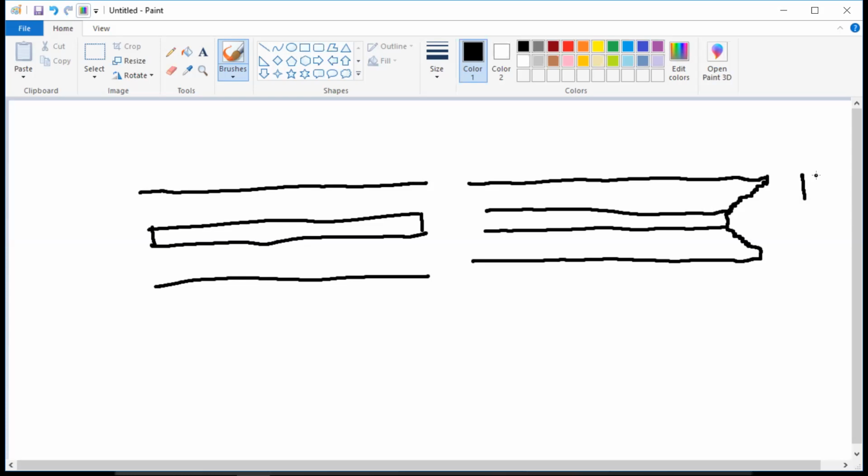Oops, Control Z. Here's the other side of it. It's going down here. Core in the middle. All right, I'm introducing my Von Thumper voltage on here, but that voltage is still not high enough to make it all the way across this insulation to ground to be able to produce a thump. That's an open conductor. All right, let me get back to the video.